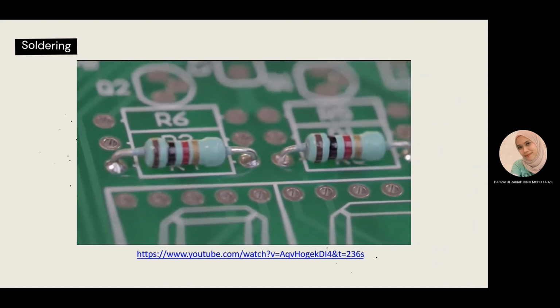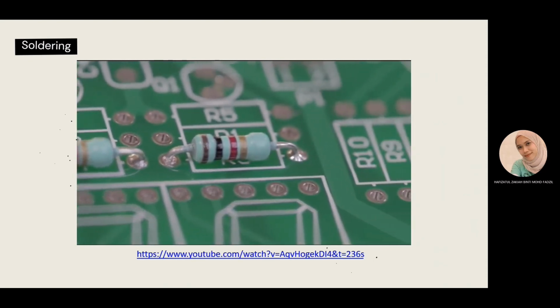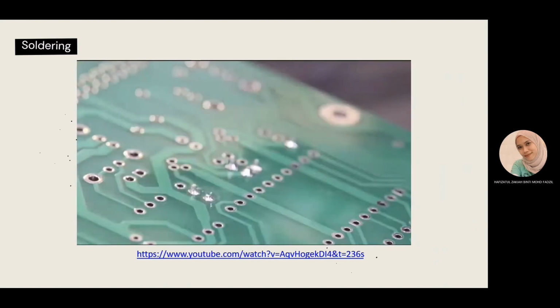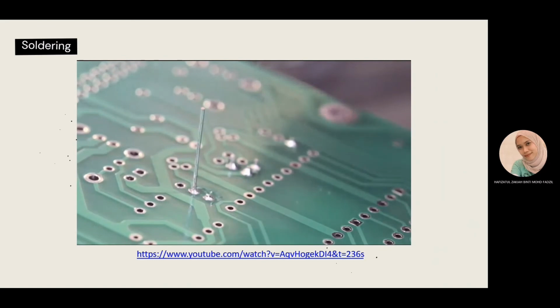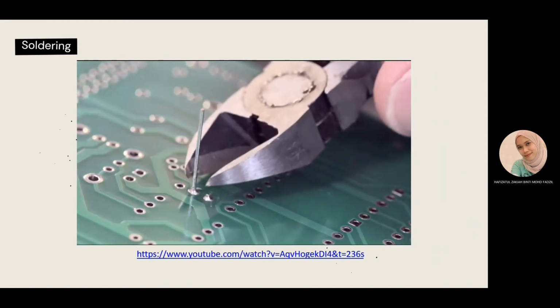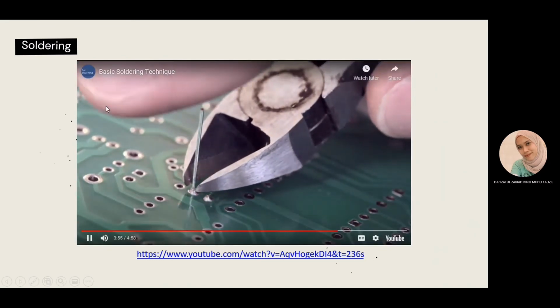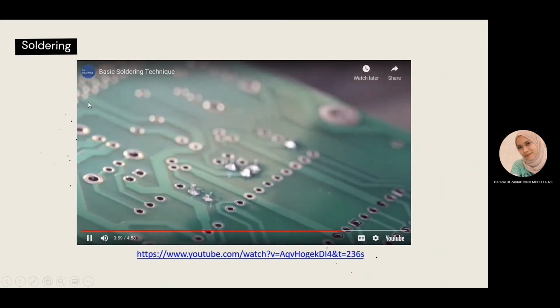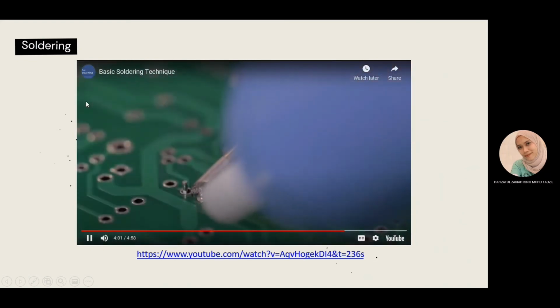When you turn the board over, you should see that the solder has flowed through the hole by capillary action, guaranteeing a good contact. Trim the leads just above the solder using some wire cutters. When you cut the wires, be careful that the cut end is held captive so that it doesn't fly off. This can be done by putting your finger on the end when cutting.